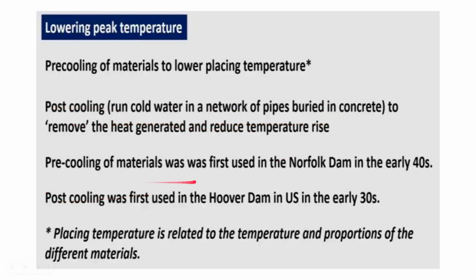As you can see, pre-cooling of materials was first used in the Norfolk Dam, in its construction in the early 1940s. The post-cooling method was initiated earlier than pre-cooling, and that was first used in the Hoover Dam in the United States in the early 1930s. Placing temperature is related to the temperature and proportions of the different materials.